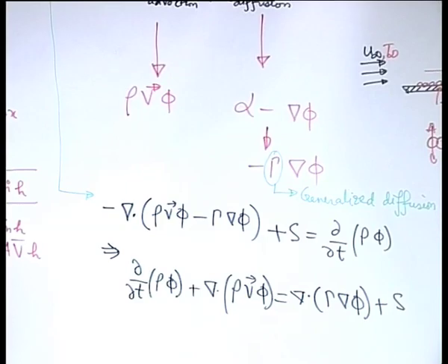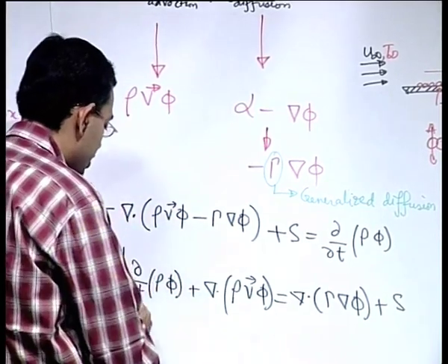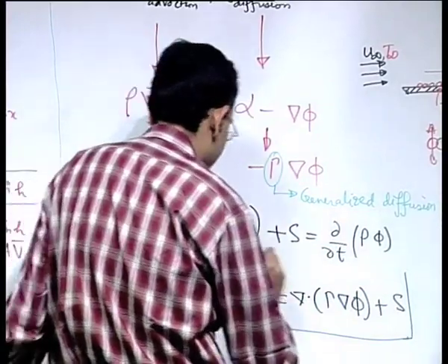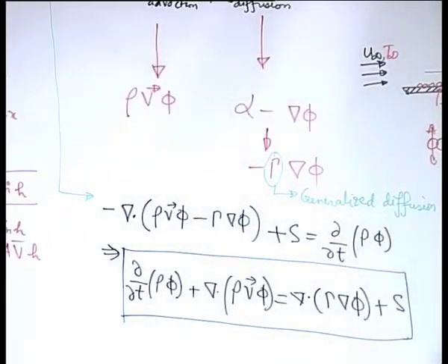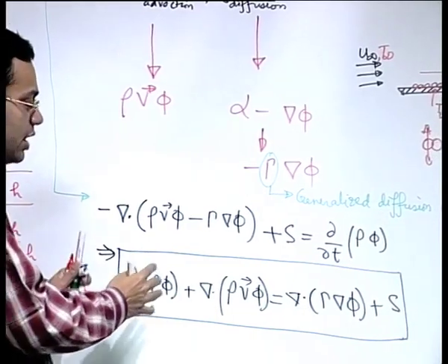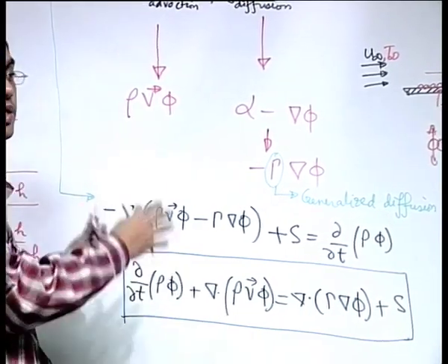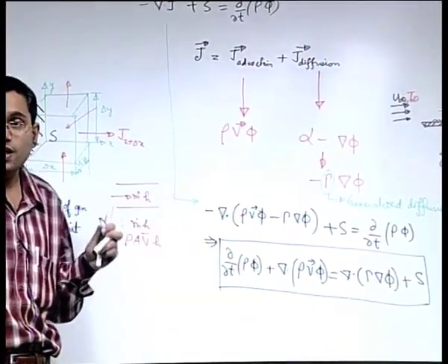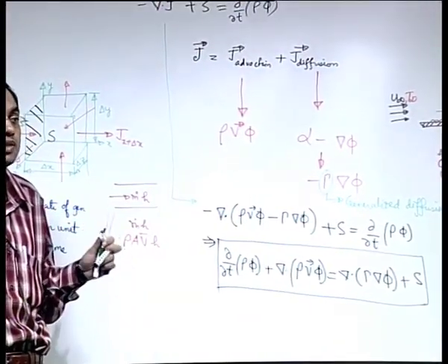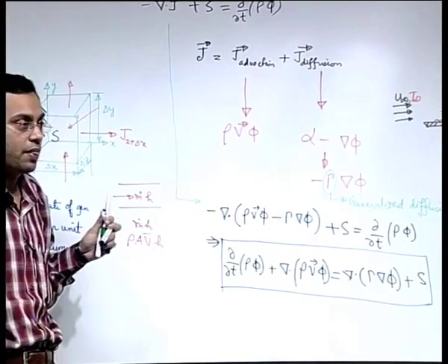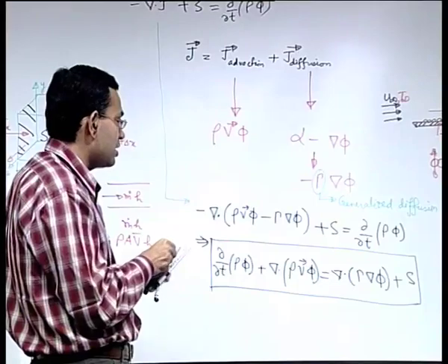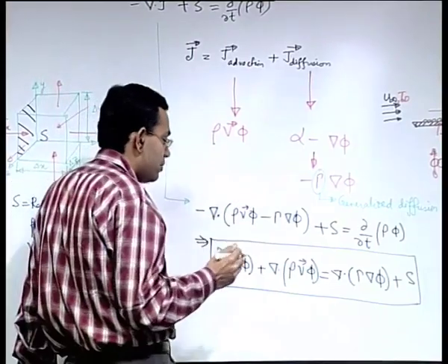This equation is like the heart and soul of the CFD course that we are going to undergo. See, this is an equation which does not tell you whether it is mass conservation, momentum conservation, energy conservation, whatever. It just tells that it is a general conservative equation where it conserves something. Irrespective of what that something is, it comes up with different terms with different physical interpretation.